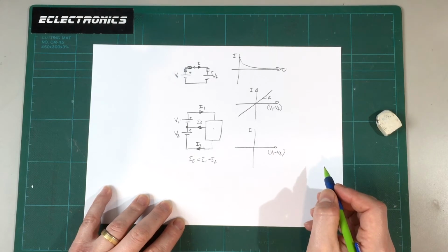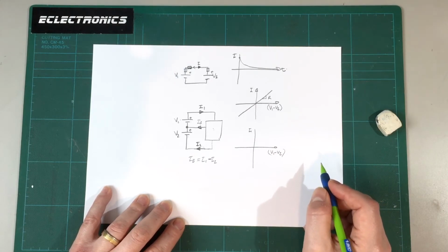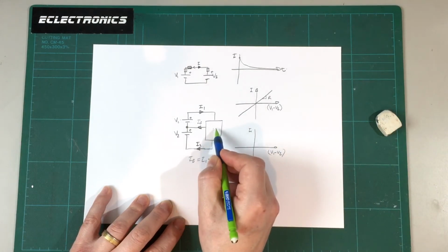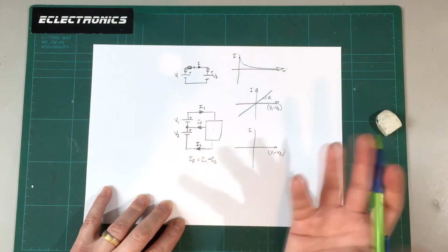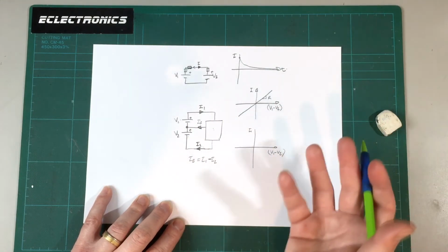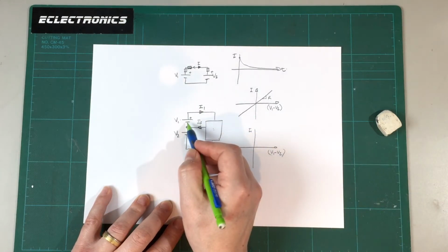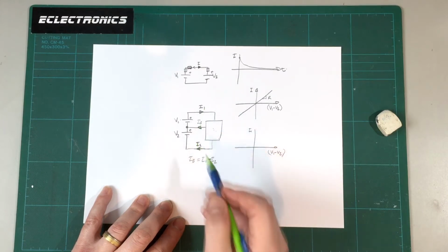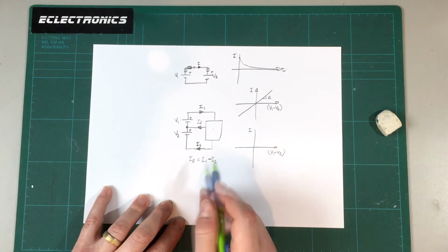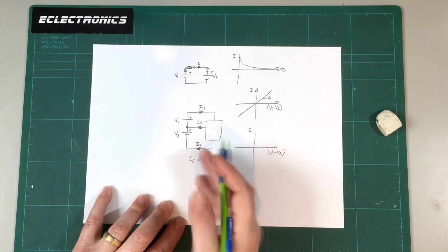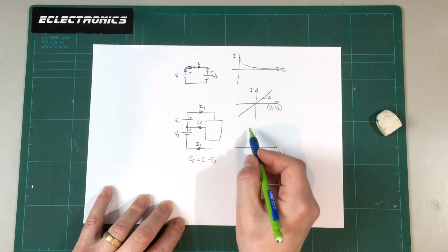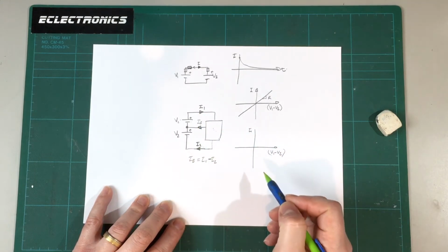And I think I1 and I2 I'd expect to be reasonably similar, because if this thing was 100% efficient, and the cell voltages are not going to be that far apart, then on those 2 assumptions, cell voltage is similar, 100% efficient charge redistribution, these currents would actually be very similar. Of course, if one cell is considerably different voltage to the other, that won't be the case. So yeah, it's going to be interesting to see what plotting the different currents gives us on here.